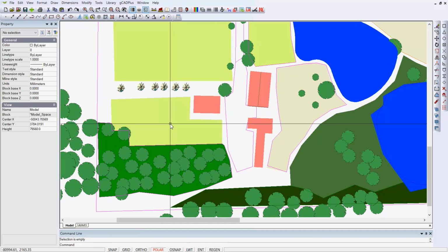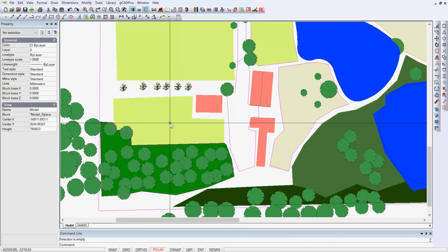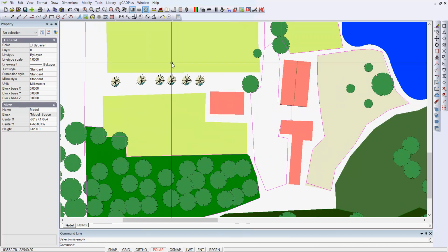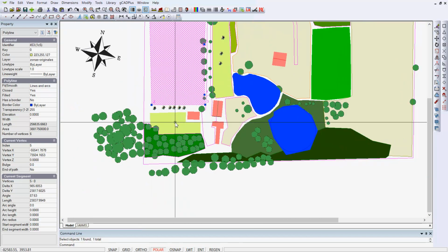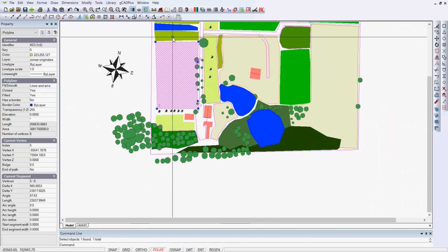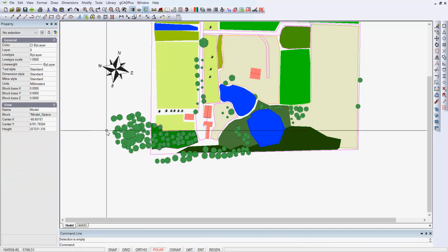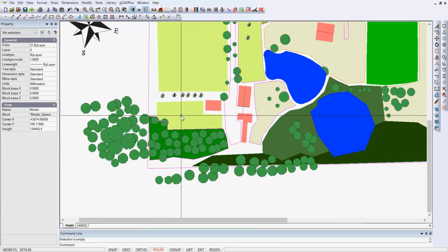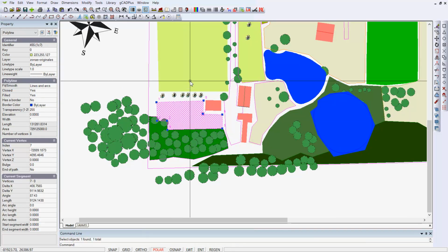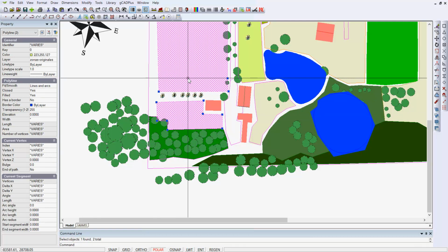So can you see that there's considerable duplication? We probably don't need 2 or 3 polylines covering the same area. We're just trying to simplify things. If you did need a border around any of these zones that we're talking about, I'll click up here and change the 1 to a plus, which means I can pick, say, this closed polyline that's filled, this closed polyline that's filled.